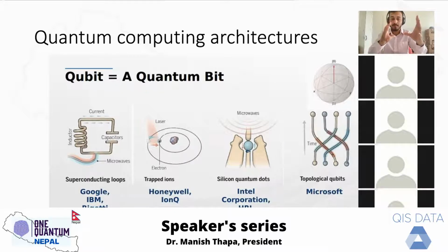And if you cool this down to 0 Kelvin, this macroscopic, huge thing can behave like a quantum particle. This macroscopic circuit behaves as a quantum mechanical system, but you need to cool it down to almost 0 Kelvin, right? And you use a dilution refrigerator, now like this dry fridge, a more recent, more advanced kind of refrigerator that doesn't use liquid helium. You need to keep this electrical circuit at those extremely low temperatures, almost 0 Kelvin, and you can build qubits.